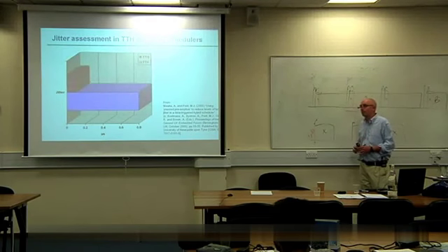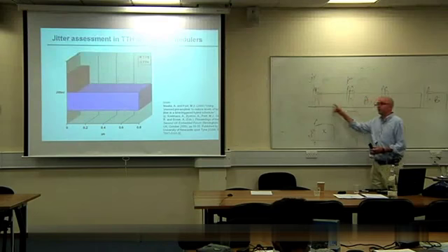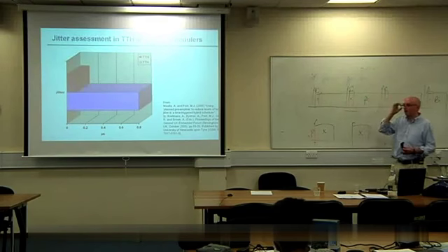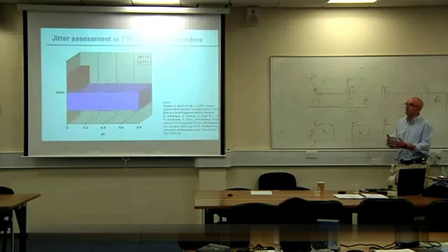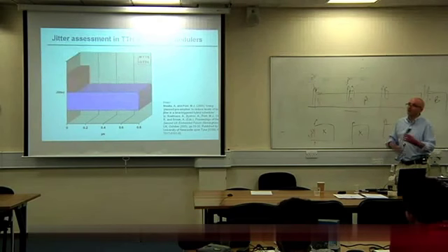Then you're in trouble. So sometimes you can, and the really ideal way of building these is completely statically. Work out exactly when the task preemptions occur and do it statically, and do it manually like that, but it's enormously time consuming. And it has no flexibility. And you have to redo it again if you make changes.